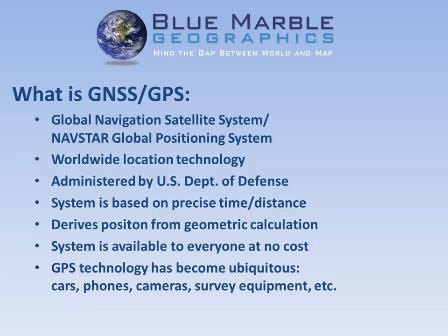Yeah, and it does also sometimes depend on where you're using the unit. Absolutely. For example, if you're using it in a busy urban area with lots of tall buildings, you might have a lower accuracy than if you're using it out where you have a super excellent view of an open sky. Yeah, those buildings tend to reflect the signal, so you're going to get a false signal as well as the original signal. So that is a consideration. Canopy is another one as well.